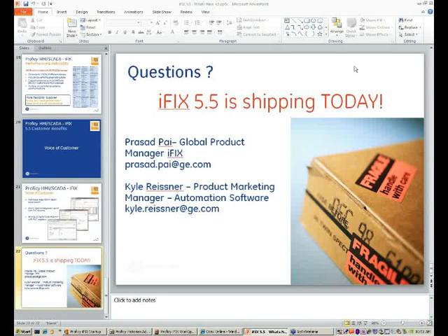In iFix 5X and ideally iFix 5.5, since you would upgrade to iFix 5.5, has a more traditional active standby concept on the SCADA. So I think that is something that you will have to watch out for. Depending on how your application is structured, it's quite possible you may not have to do any changes there. But I know customers who had written specific scripts around the way 4.5 failover worked, and you'll have to watch out for that behavior of the SCADAs.